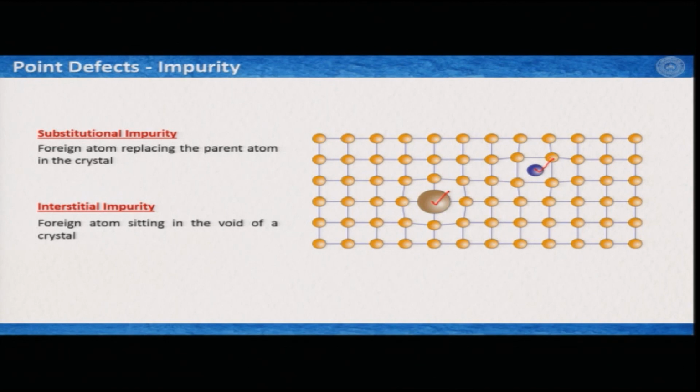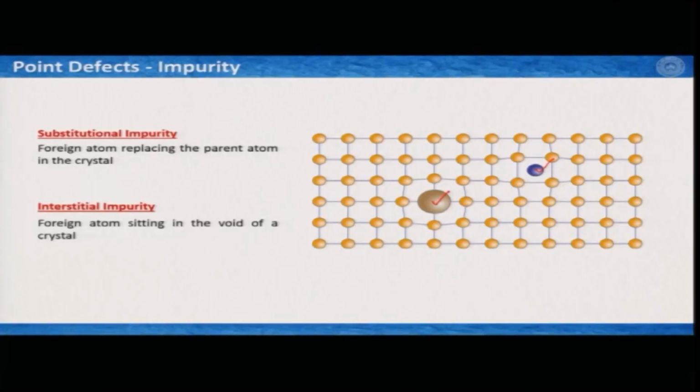Now, most of the gemstones that we see or that we are aware of are actually results of substitutional impurities. I give you an example, ruby. Ruby we know is a fantastic gemstone, it is red in color, but the host mineral of ruby, the actual mineral of ruby, is nothing but corundum, it is aluminum oxide. Now, if the chromium atom replaces 1% of the aluminiums inside this corundum crystal, then it becomes red, and that is why it becomes very precious to us because of this red color. So, it is not a pure crystal that we see as ruby, it is actually corundum, aluminum oxide, and in one site, the metal site, we have aluminium replaced by chromium, and therefore, we see the red color, and that is why it is expensive.